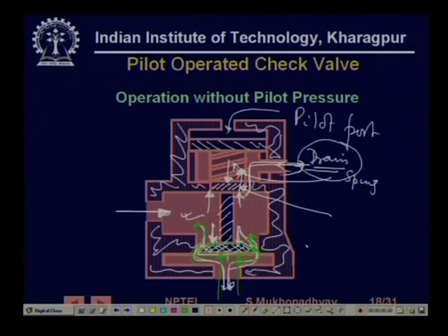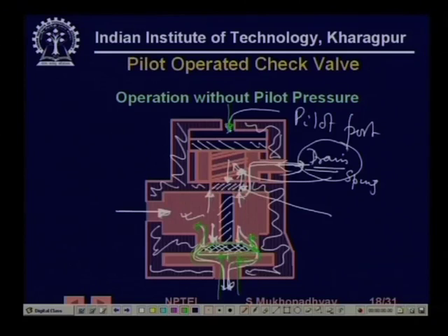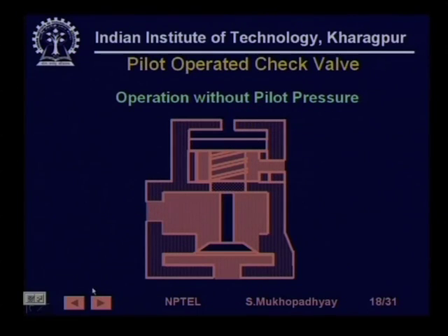On the other hand, if in certain conditions we also want reverse flow, we can apply pilot pressure here. If you apply pilot pressure, then this whole thing will come down. We have a separate diagram for the pilot pressure, so we will show that.